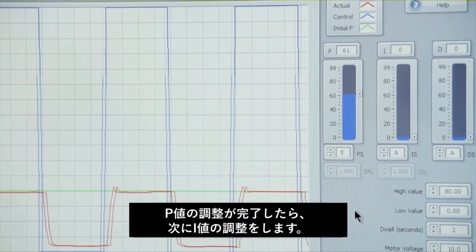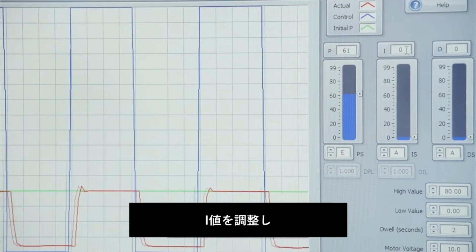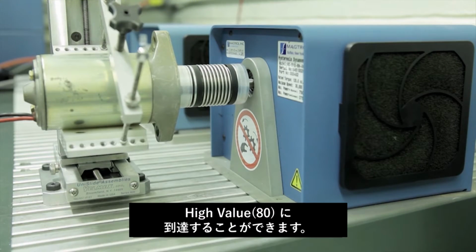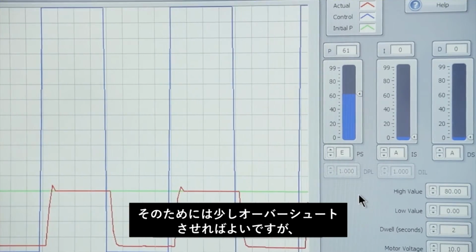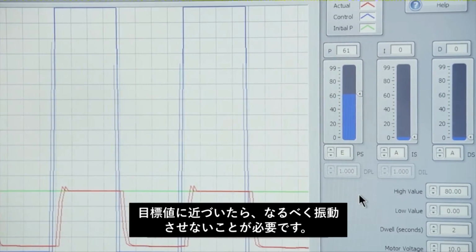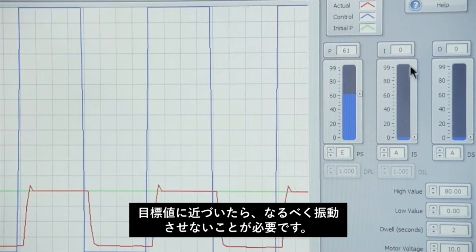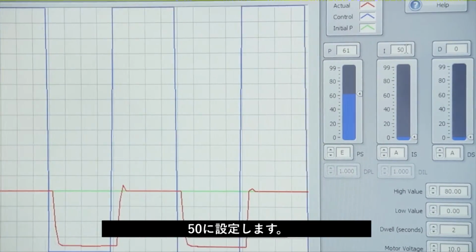Once we've achieved that, we need to focus on the I term. Now the I term is going to cause our system response to come up to our target value. What we're looking for is a fast response, and generally you get that by adjusting for a small amount of overshoot, but you also want it to become stable so it cannot oscillate much once it reaches that target. So again, we start with a number in the control. Let's put 50.